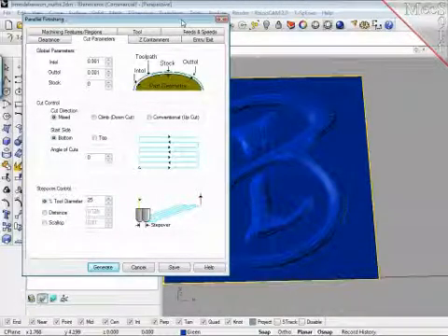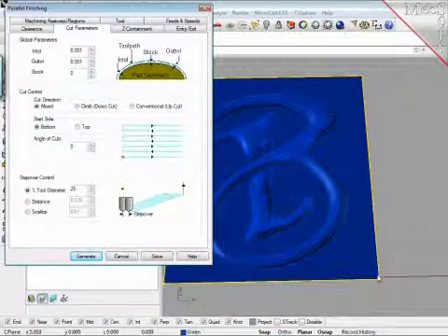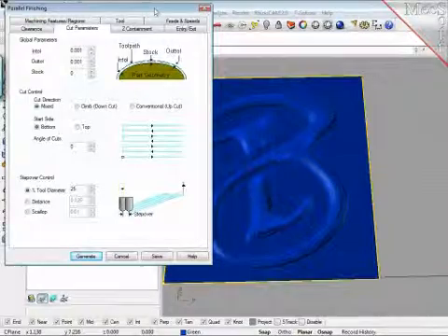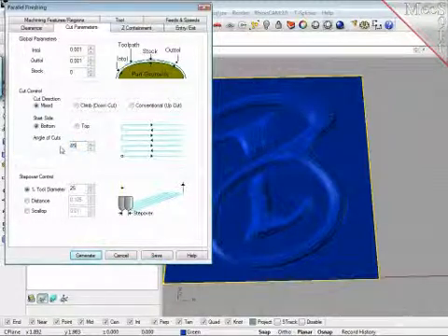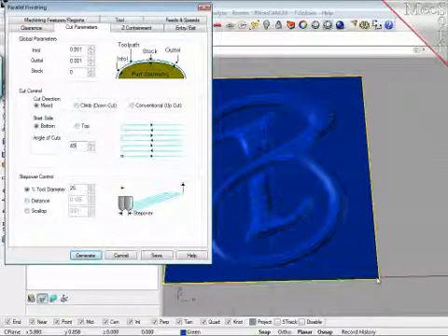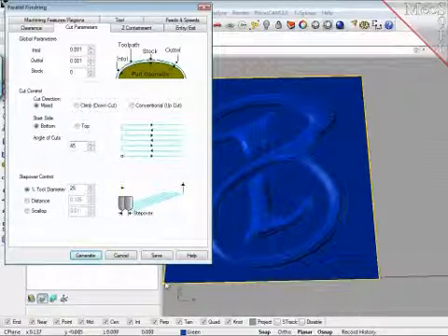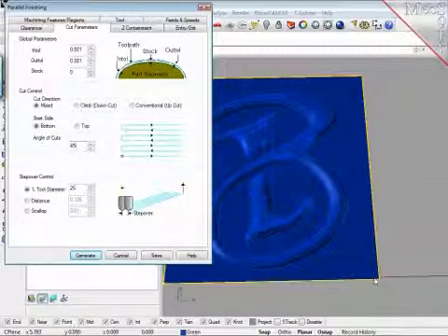And here, angle of cuts is a very, very important part in woodworking, specifically when we make our life easy here in just using one method to cut the entire piece. Angle of cuts, I'll set this to 45 degrees right away, because if the cutting tool would go back and forth to cut out the shape through solid material, if it would dive in here and cut over there, it would be broken till it's here, because it would have to dig an enormously deep trench with a very, very small tool, and the probability is very high that there is a little piece of material wedging in and just snapping it off.